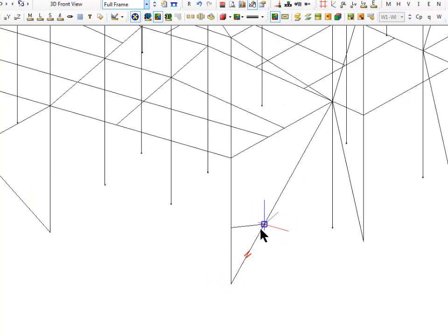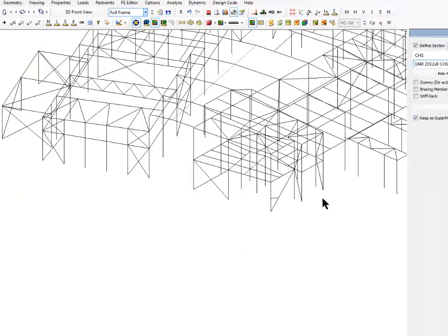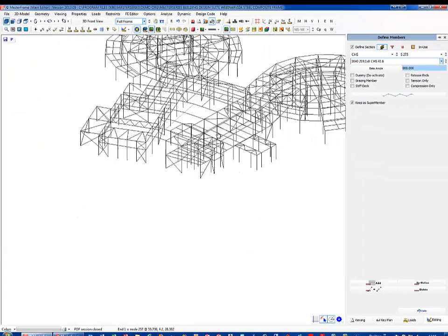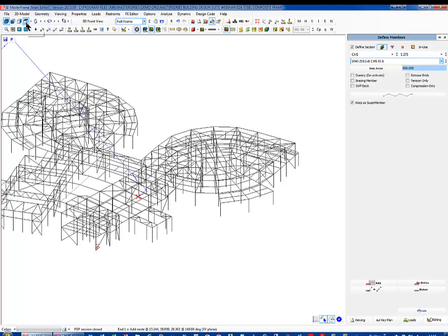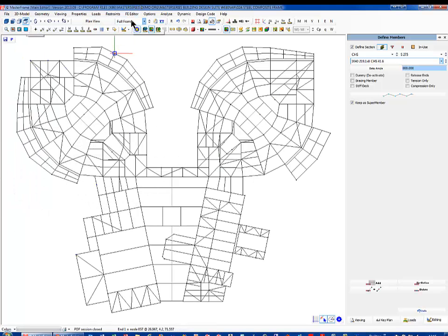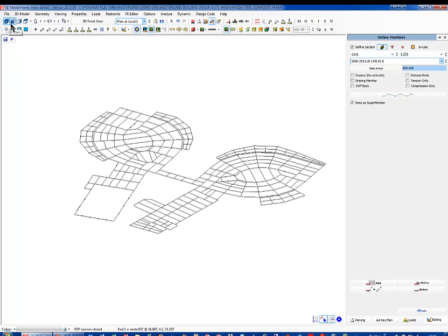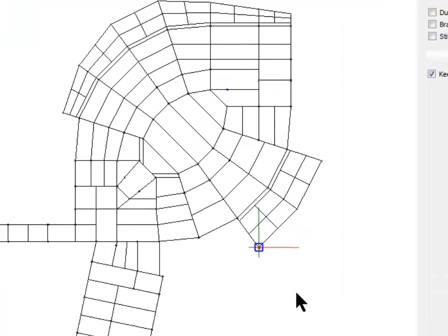So I have fantastic editing tools here, and we'll see these in great detail if we put this frame in, say, in the plan view. And I'm actually just going to look at plan level 1. So that's going to show me a flat surface plan. Now, if I wanted to create another member coming out from this one, another one coming out from that one, I'm going to have to work out all my fancy coordinates, or I'm going to have to introduce grid lines. I actually do have grid lines, but I'm not going to worry about them.